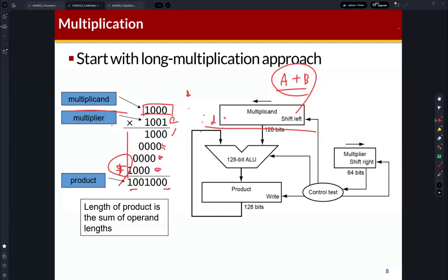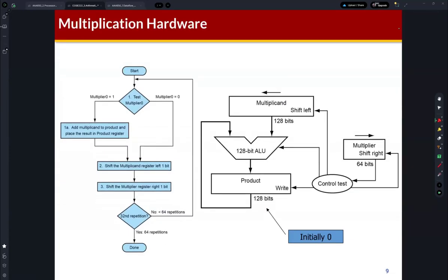For this digit, there is no shift, and then for the next digit, we need to shift left by one digit. Then shift left by two digits, and three. Then we can accumulate these generated partial products. So this figure shows the shift operation for each digit of the multiplier, and then it's accumulated.